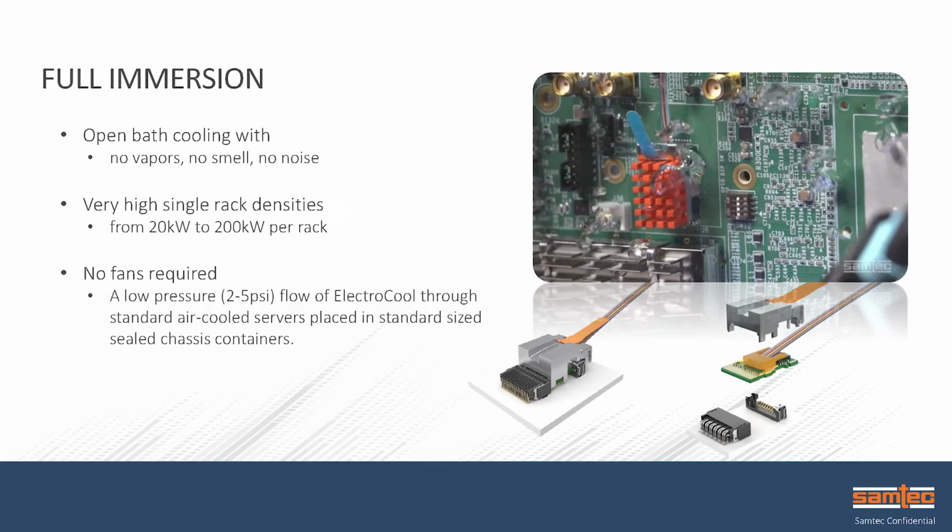So now let's take a look at full immersion cooling. These are different methods of creating this system, from an open bath to a closed system. You can do very high density single rack systems from 20 kilowatts to 200 kilowatts per rack. There's no additional cooling fans needed, and typically it's a much lower pressure to circulate the coolant fluid.